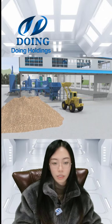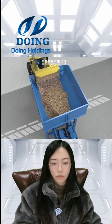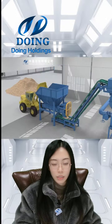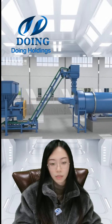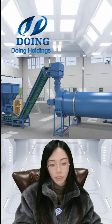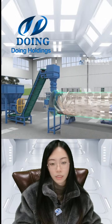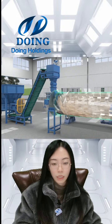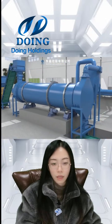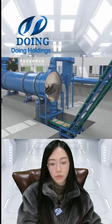The physical changes are mainly the dehydration, degassing, and drying process. The chemical changes are mainly two types of reactions: thermal decomposition and thermal condensation. The process consists of three main steps: pyrolysis, carbonization, and cooling. Cooling is the process of cooling the freshly formed charcoal at room temperature so that it cures into the final product.